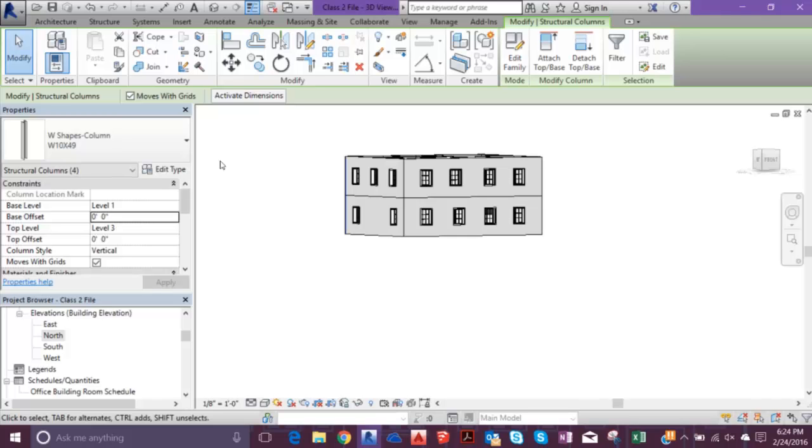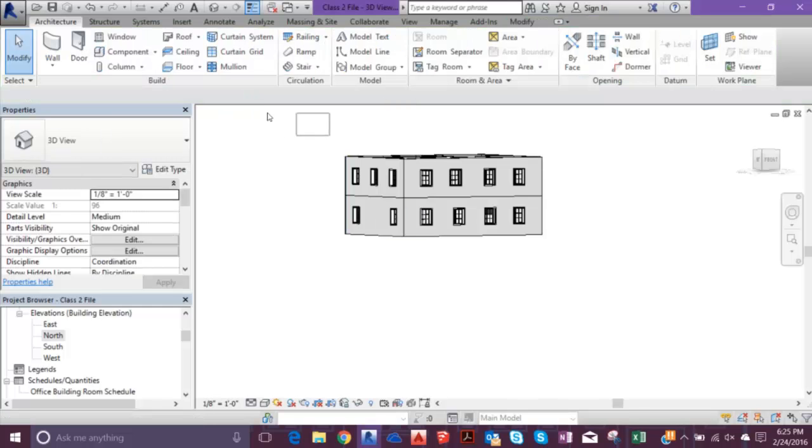Likewise, if you want to bring it down some and extend it like this, you can go -2 foot. This works the same way with the top offset, except top offset is flipped, so you would go downwards rather than upwards with a positive number. Okay. So now what we're going to do, thank you for that, by the way.